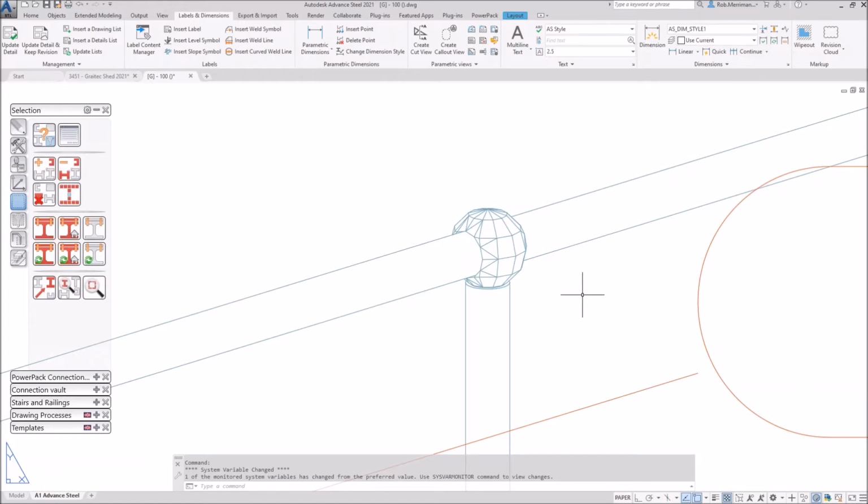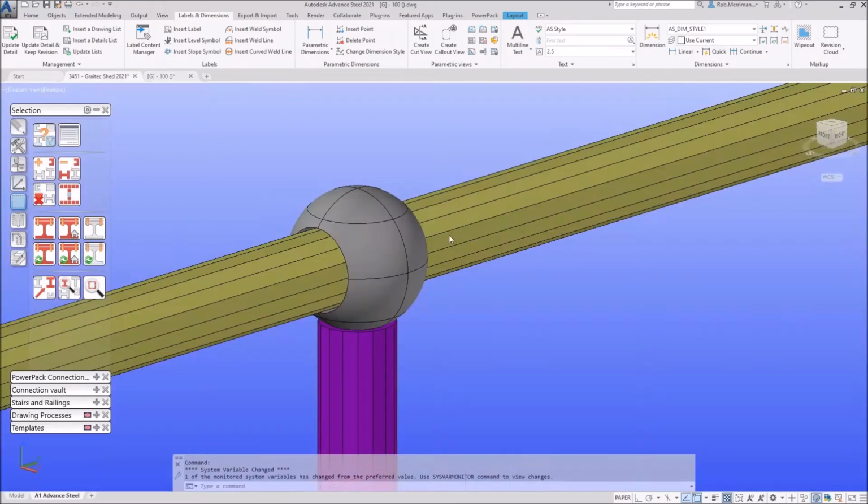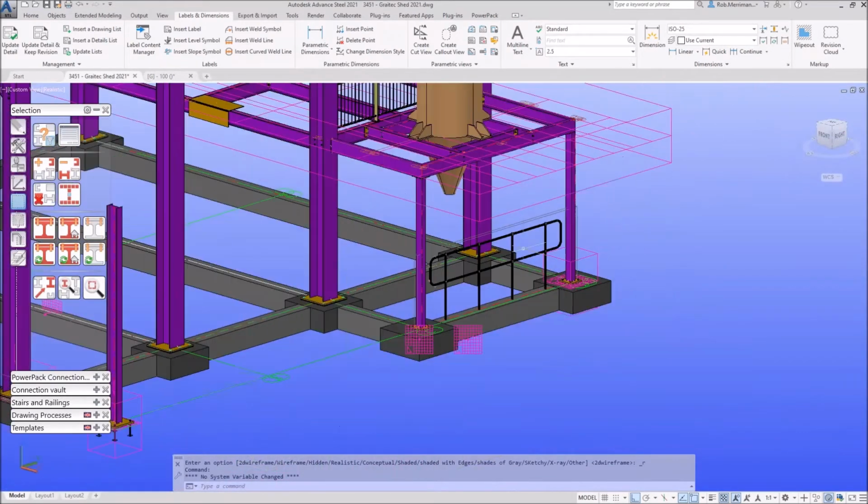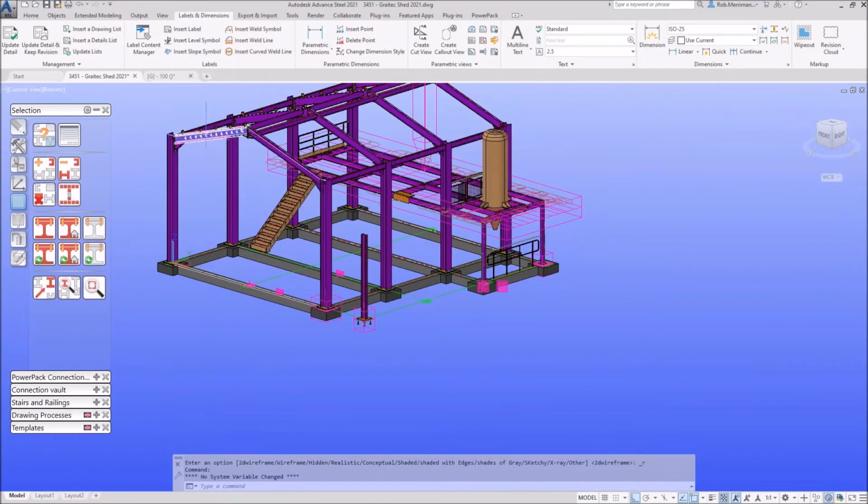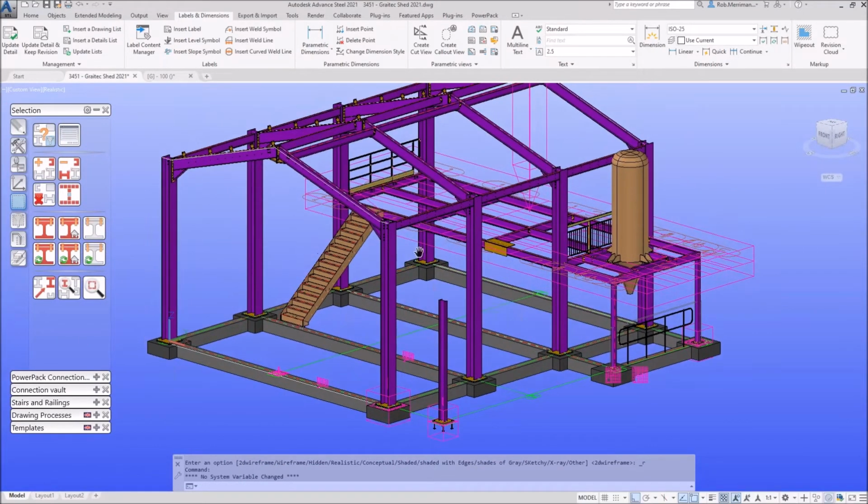I have done a webinar on special parts, which can be found on our content portal. And in that webinar, I do talk about keeping the special part as simple as possible. The simpler it is, you don't need to radius and chamfer every corner and edge, because that will give you more tessellation lines. So the simpler you keep your special part, the better.